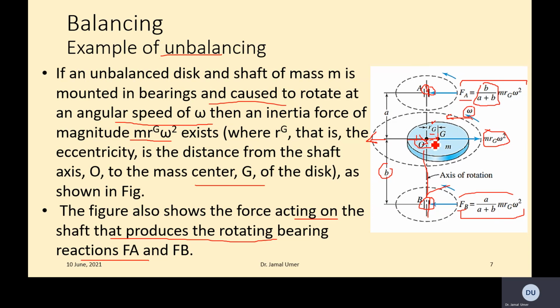You made a disc and its center of gravity is sitting somewhere over here, and then you have the attachment. So the net result is that this comes from the manufacturing process. The manufacturing process is not quite accurate, and that has resulted in forming this eccentricity. This is one thing I was explaining: why the eccentricity is present.